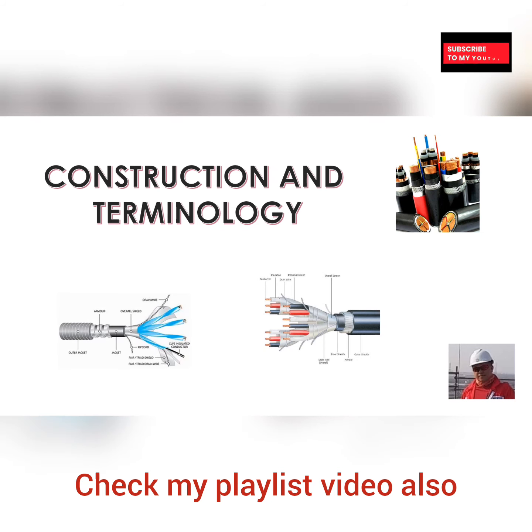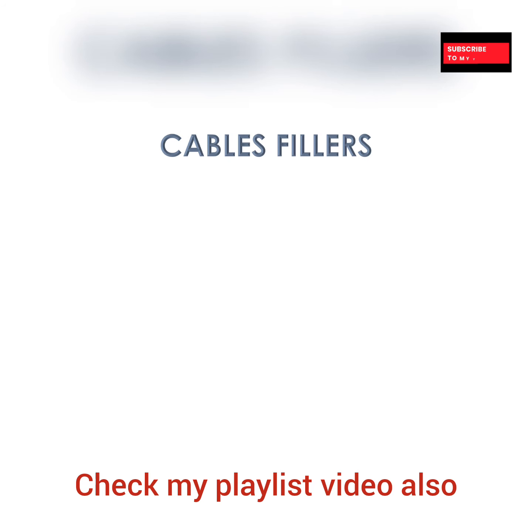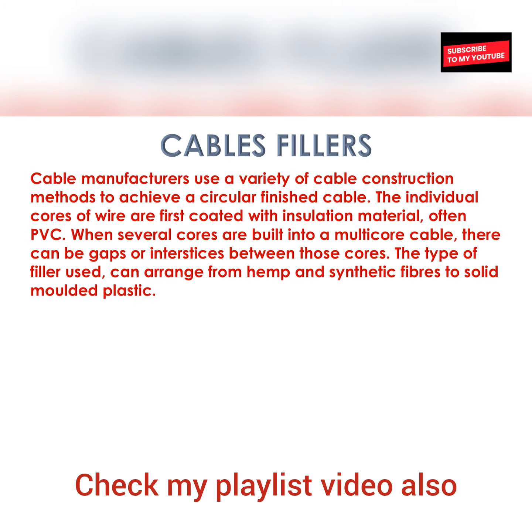So we are now going to constructions and terminology of those cables. You can see these are the cable samples: shielded wire cables, armored cables. So, cable fillers. Cable manufacturers use a variety of cable construction methods to achieve a circular finished cable. The individual cores of wires are first coated with insulation materials, often PVC.